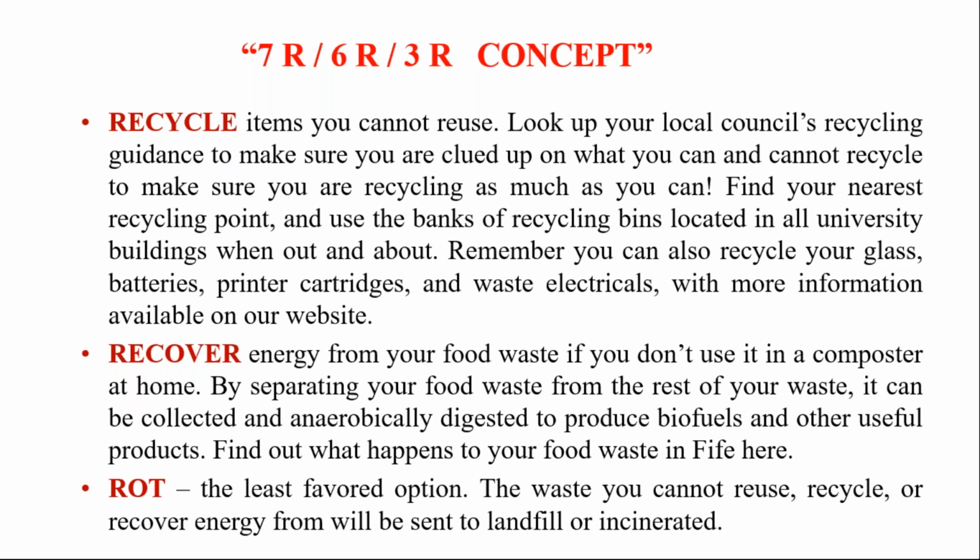If you are going to burn this waste, then you have to take care of the SOx and NOx, that is sulfur derivatives and nitrogen derivatives. Then you also take care of the carbon percentage or the hydrocarbon or some other gases, that is called flue gases, that is, after-combustion gases. And we have to treat some of the gases if the maximum permissible limits are exceeded. So for that purpose, in some of the setups, a scrubber system should be incorporated in the plant also.